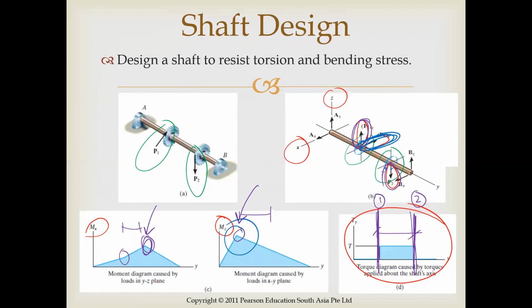Not necessarily the case. The way that welding works is that the more weld material you add, the more vulnerable that weld is to fracture. You have a bigger weld, it's more vulnerable to fracture. It might actually be weaker than if you had a smaller weld. So you only want to use as much weld material as is absolutely necessary.